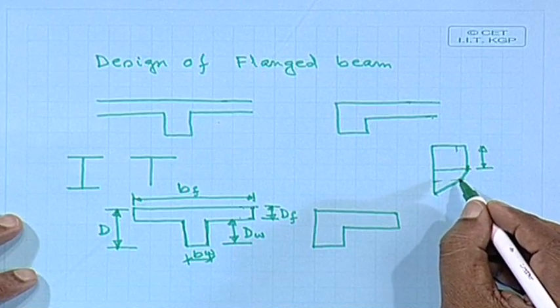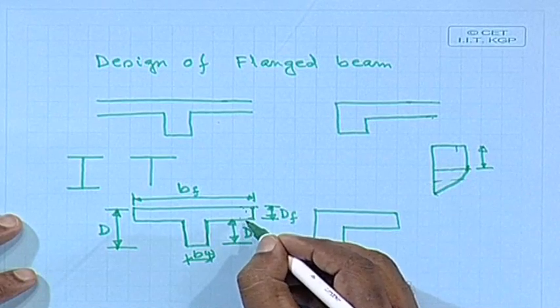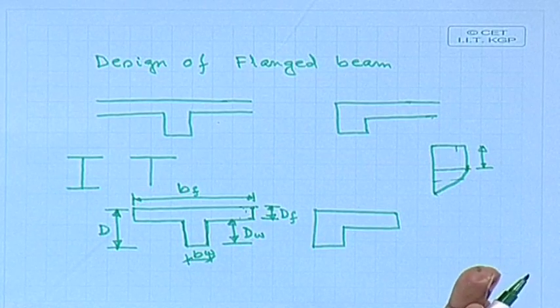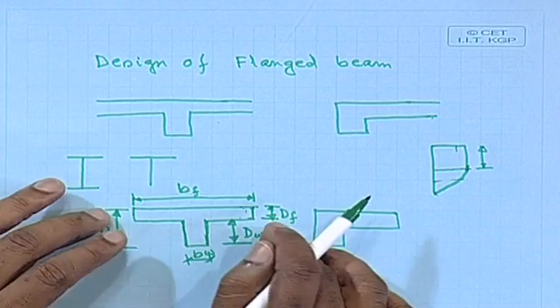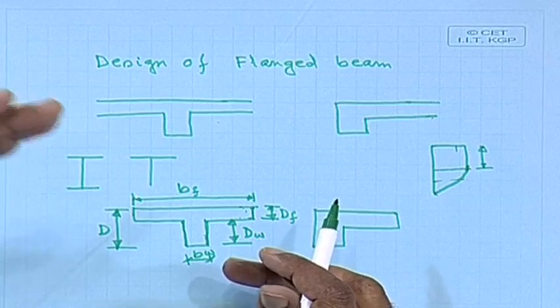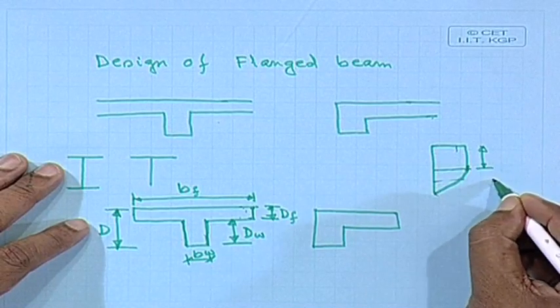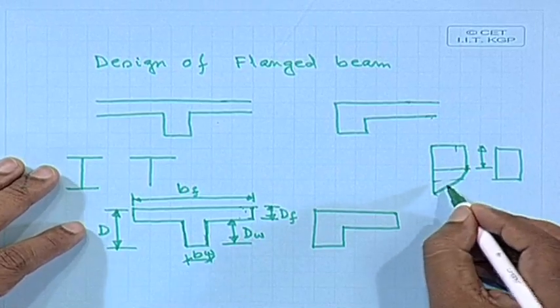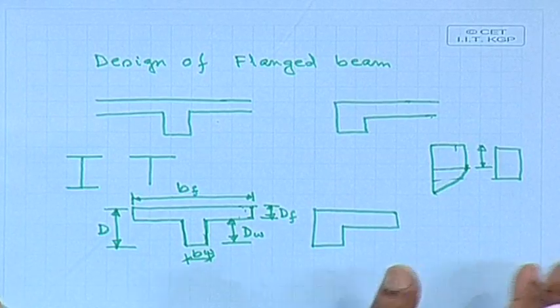So, which is the most difficult one? The first one is easier, it is nothing but the simple rectangular section, only instead of using B we shall use the BF. The other case also we shall have two parts, one part is the rectangular portion, other part is the flanged portion, but it is having constant stress. So, we can get the force easily, but the third part where you are having somewhere in between the flange, then it is a difficult portion, that how much will be the force, that also we can find out. So, these are the three different cases, and that we shall continue in the next class. Okay. So, thank you.